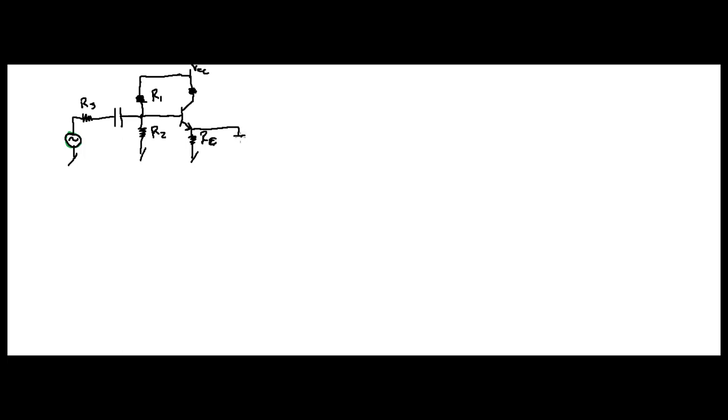Okay. And you also have a capacitor, and this goes around it as well. Now, this is a bypass capacitor. We can call this, if you want, C2. We can call this C1. And you're going to have another one tapping right off your collector, coming through a coupling capacitor, and it comes over here through your load resistor, RL. And this up here is RC.